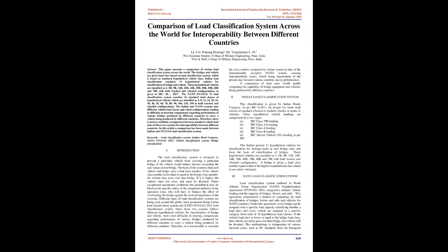Under exceptional operational conditions this prohibition may be lifted on the specific orders of the competent authority in the operation zone, who will have to balance the effect of overloading the bridge against the tactical importance of the crossing. Different types of load classification systems are being used around the globe, the most prominent being the Indian Load Classification System and the NATO STANAG 2021 Load Classification System.